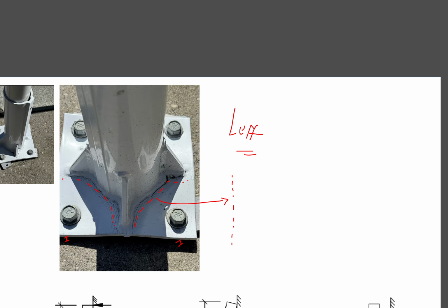This is why people use stiffeners to stiffen up the edges: you can mobilize more yield lines. Imagine without this stiffener, your yield line would go around like that. It is obviously shorter than having a stiffener in the middle, breaking it up, so you can have more and longer yield lines. So more yield lines, the better.